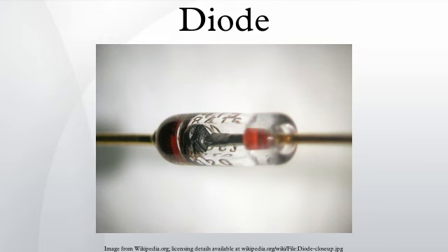Shockley diode equation. The Shockley ideal diode equation or the diode law gives the I-V characteristic of an ideal diode in either forward or reverse bias. The following equation is called the Shockley ideal diode equation when n, the ideality factor, is set equal to 1, where I is the diode current, I_S is the reverse bias saturation current, V_D is the voltage across the diode, V_T is the thermal voltage, and n is the ideality factor, also known as the quality factor or sometimes emission coefficient.